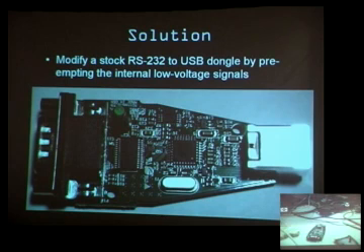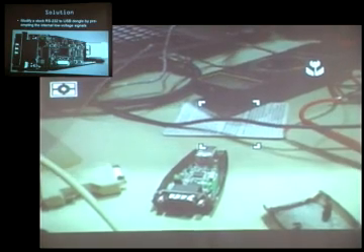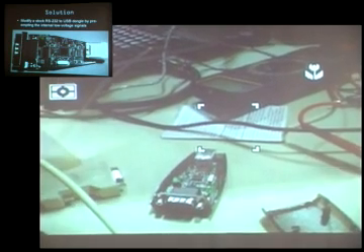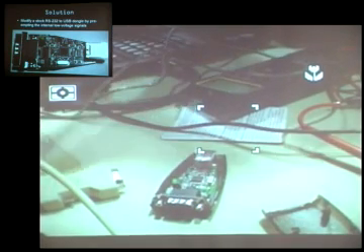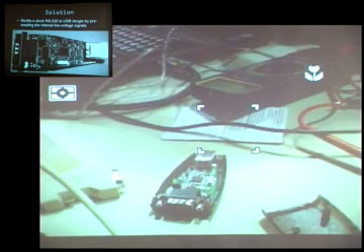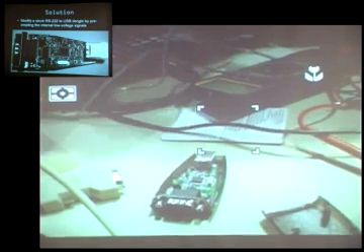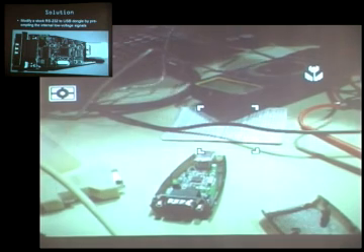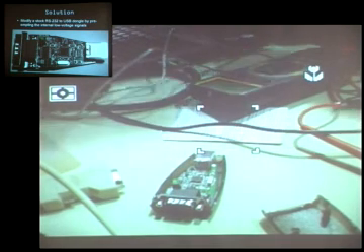Here's a picture of it up on the main projector over here. Now you're looking at a device you can take USB and translate to the old standard RS-232. Now remember, you didn't want to plug that directly into your embedded microprocessor because you'd break it. So what you're looking for is some internal signal inside of here that actually is at the right voltage level.